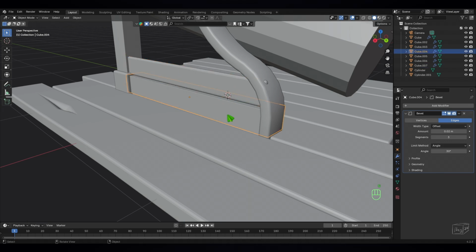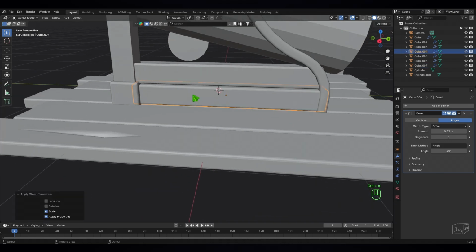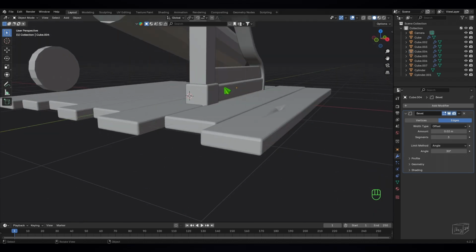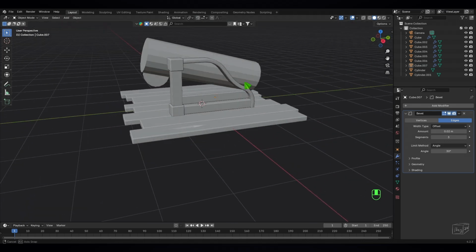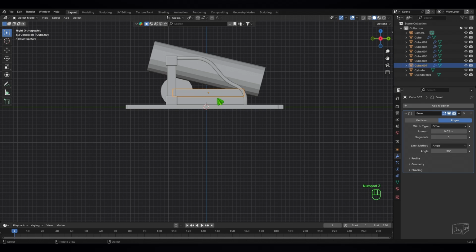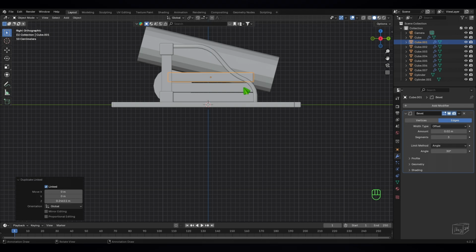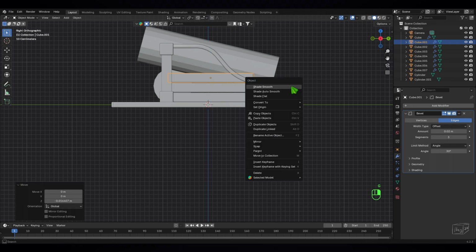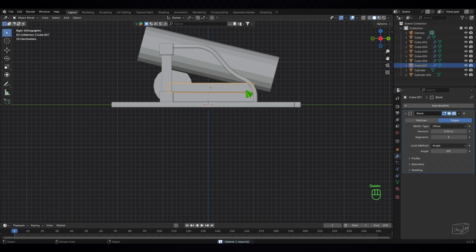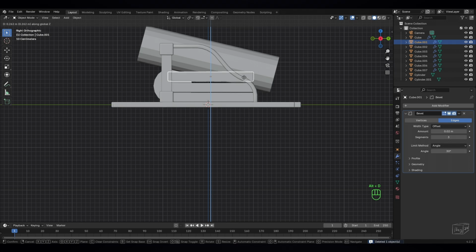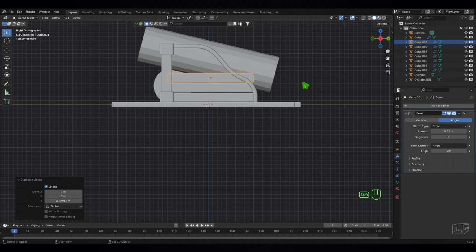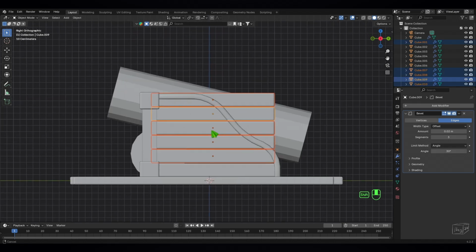Down. You see, this is different because we didn't apply the scale. Now it looks nice. Okay, now let's move it inside a bit. Okay, that looks nice. Now we have to Alt-D to duplicate it up, and you can repeat the same thing. But let's delete it for now. Let's duplicate Alt-D to the Z-axis and Shift R to do the same command.